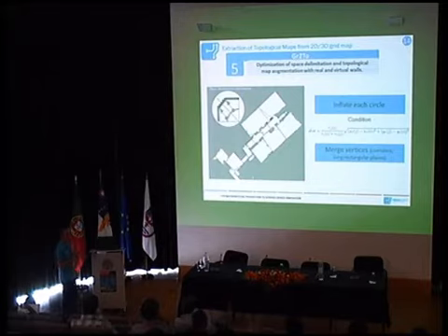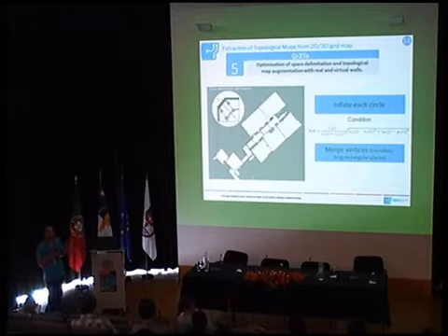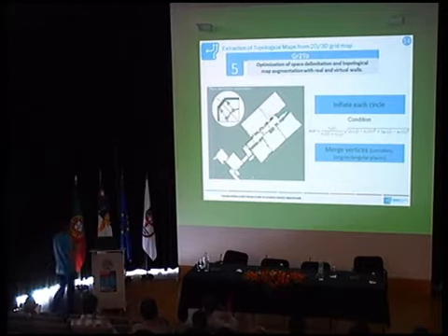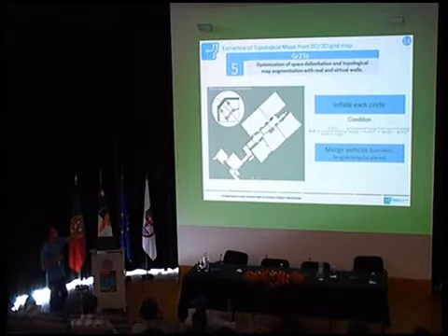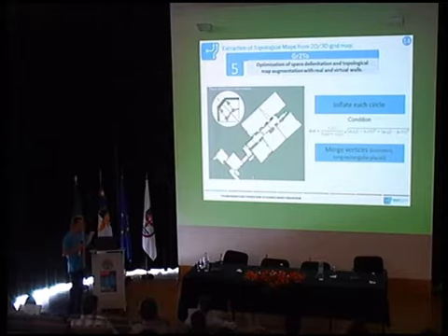What defines real and virtual walls? A virtual wall is a wall that doesn't have any occupied cell. A real wall is a wall that is over the occupied cells. If you imagine the edge of one of these inflated octagonal delimitation places, if that falls on top of occupied cells, this is our real wall.